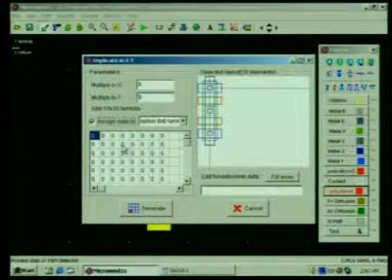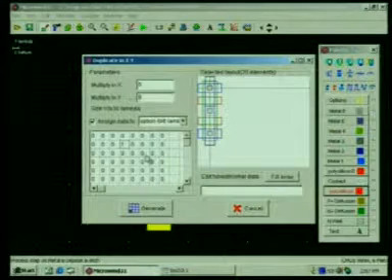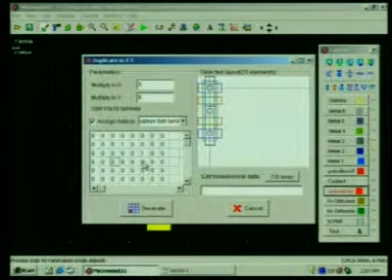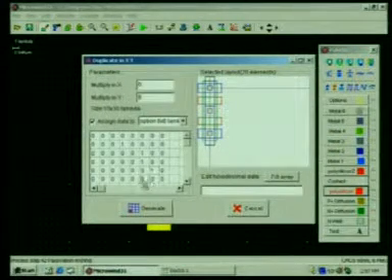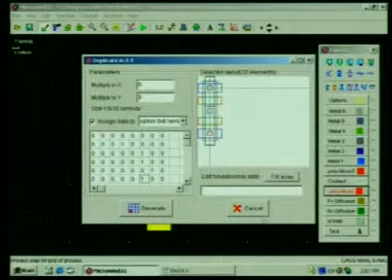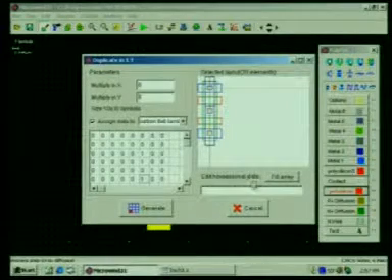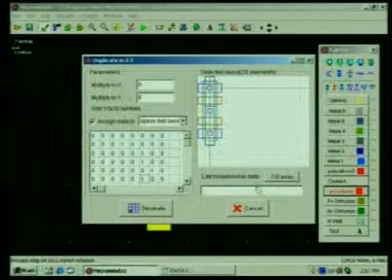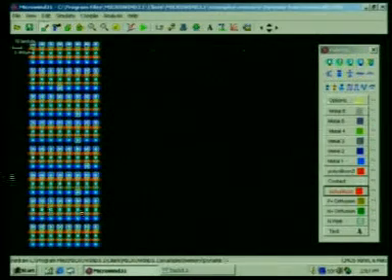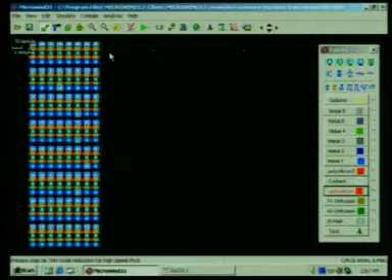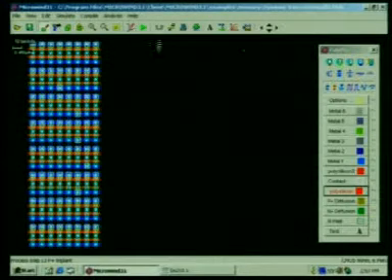Now, you can assign the value, what data you want in the memory, binary digits. Just double click, 1010 format, or you can go for hexadecimal data. It will automatically convert that into binary. After that, generate. Now it is generated, and according to your requirement, just utilize that memory and optimize that according to the area constraint.